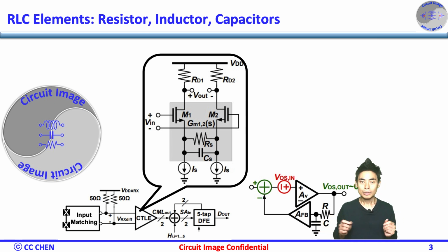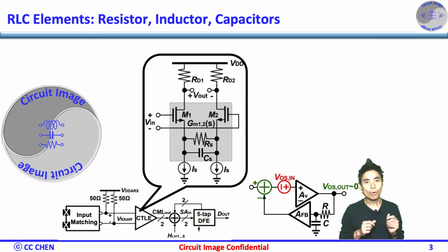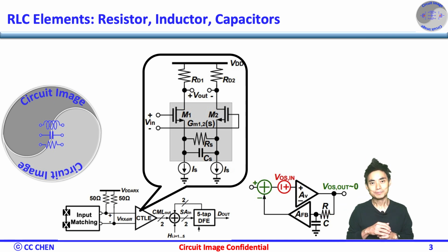Therefore, the pole, zero, or the bandwidth will determine the required area from both the unit size of the resistor or capacitor. In addition, the capacitor is a good decoupling or bypass with low impedance for the supply integrity improvement in the high-frequency supply noise ripple.